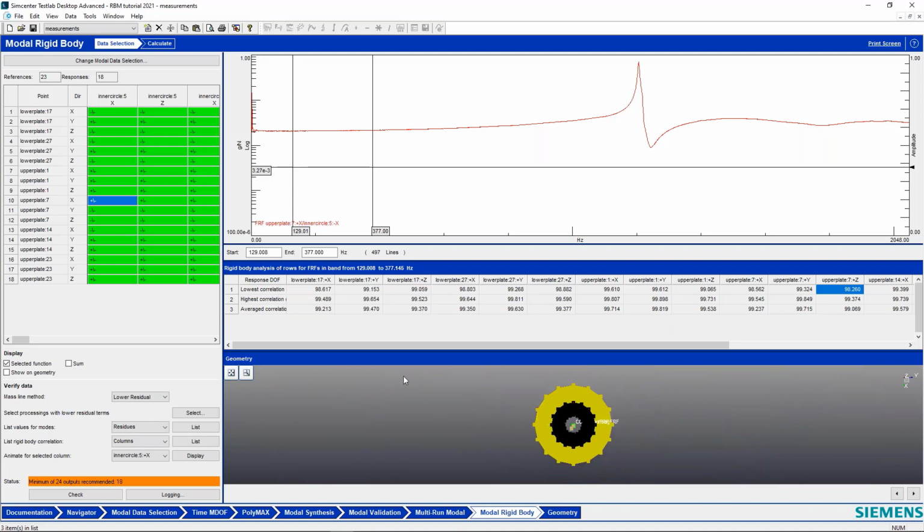Okay, so let's say I wanted to improve even more. Let's say either the corrected FRF or the unchanged FRF is getting me good results. So what else can we do? Basically, let's calculate this correlation of my columns. Then I can see across this, for each one of these references, the lowest correlation, the highest correlation, and the average correlation.